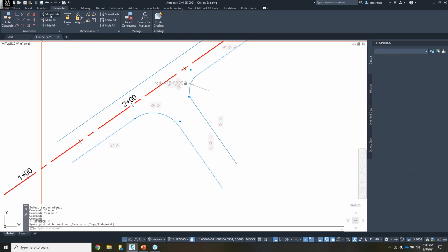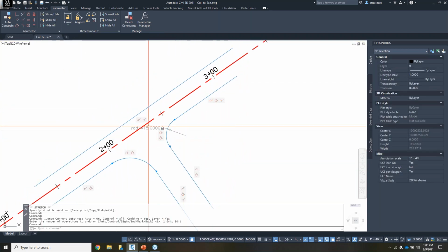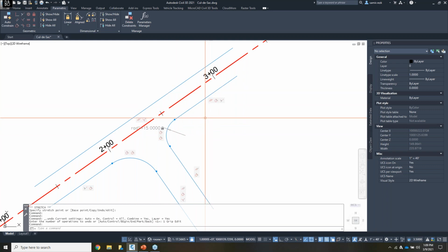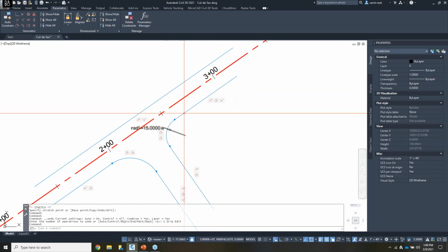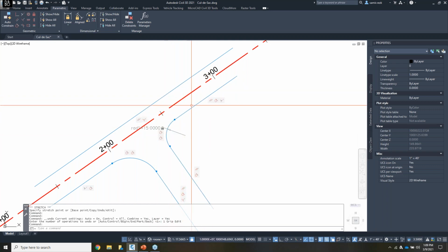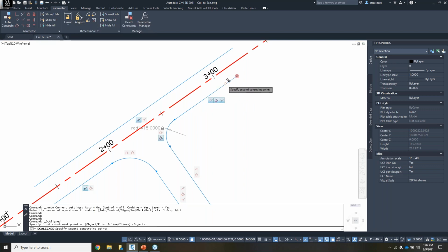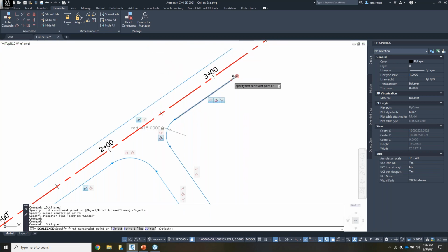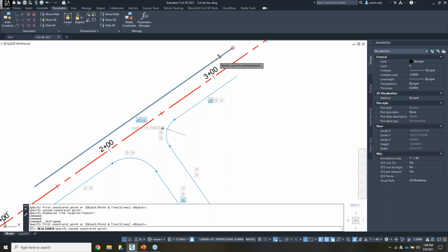So the drawing site plans like this, or maybe striping plans where you have a lot of dash lines for lanes and lines parallel to a curved line, and you can start seeing that the geometric constraint really helps you a lot with maintaining the geometry relative to other pieces of geometry. I can also apply a distance between the lanes here, and that will keep its shape.